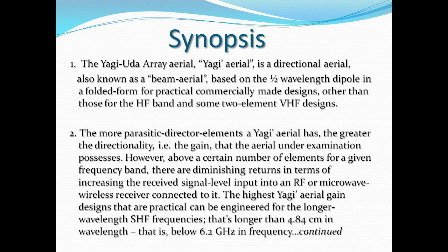The highest Yagi aerial gain designs that are practical can be engineered for the longer wavelength SHF frequencies, that's longer than 4.84 centimeters in wavelength, that is below 6.2 GHz in frequency.